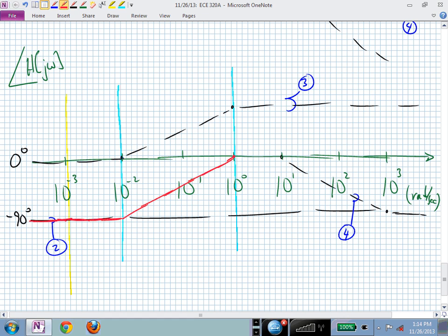Now what do we do? Now we quit sloping, don't we? The 0 leveled off at that point. So now we need to be flat. And then we say, oops, we have another factor coming in, and we need to worry about it turning on and turning off. It turns on, and actually we can just follow it down. And there we are. And that's now our total phase curve. Now I could ask you, what's the slope of the phase curve at high frequencies?